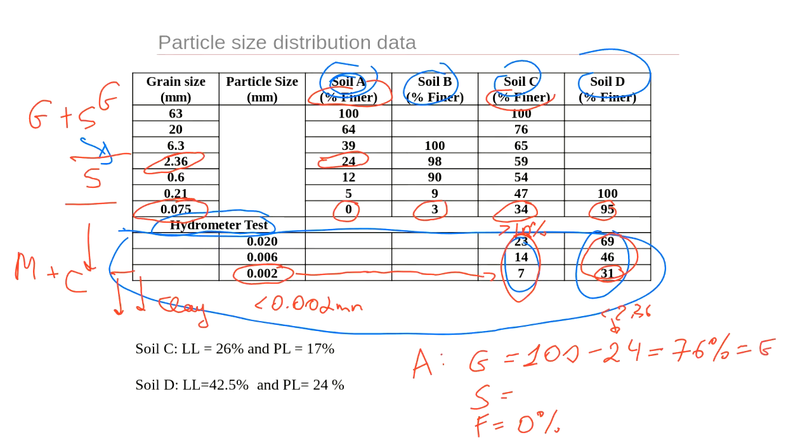And then what we do next is for sand, we take 24%, because we know the remaining percentage is 24, because 76% is already gravel. So it's already stuck in that sieve of 2.36 millimeters or even greater sieves. So we know that only 24% is left.